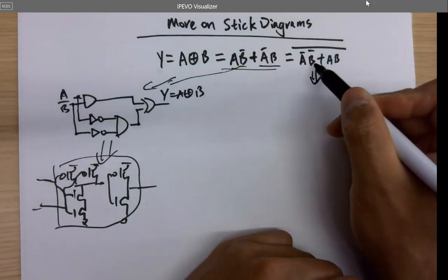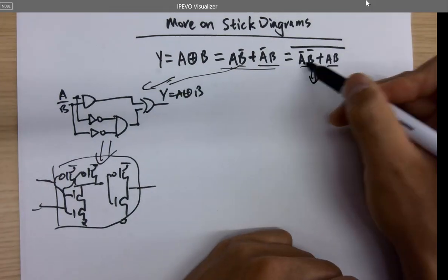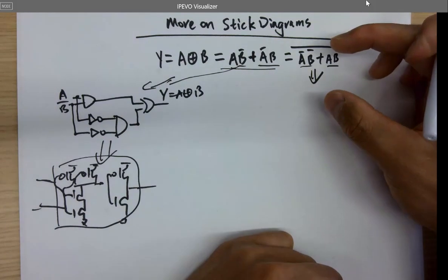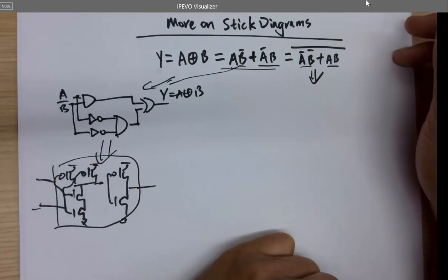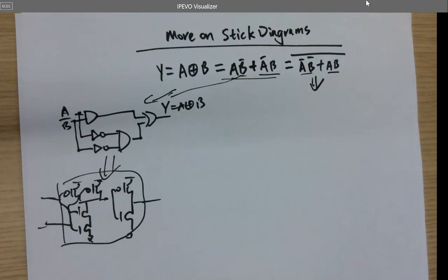Okay, and these two blocks are being ORed, so these two blocks have to be in series on the top for the PMOSes. Okay, I'll let you guys do it yourself. Take a few minutes and draw it. It's okay if you cannot finish it. So I'm going to draw the result in a few minutes. Yeah.